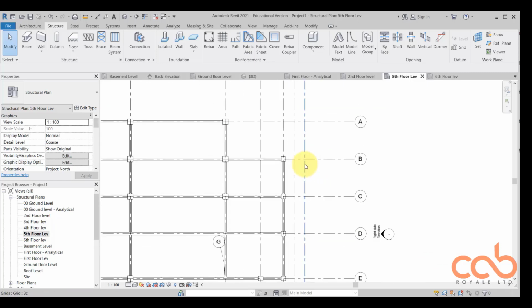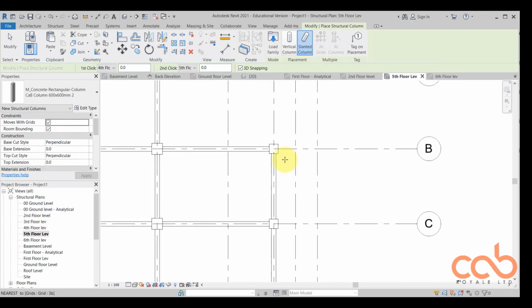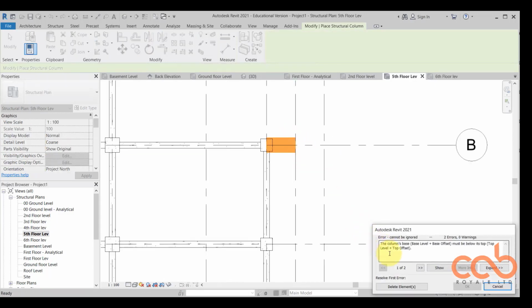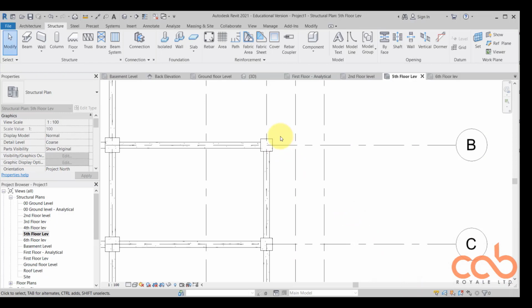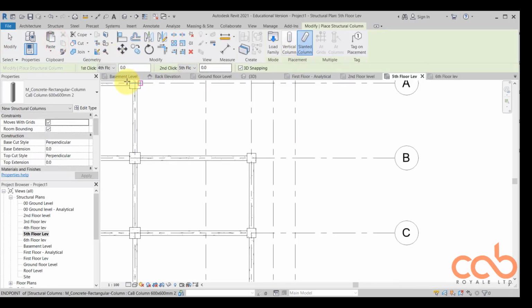And now we want to draw our column. So we come in here and pick the standard column we should be using. And this time around, we choose slanted and not vertical column. So you click here and you click on the next joint. What happens is you place the column, choose the slanted column, and then it's asking you at which level do you want to click first?